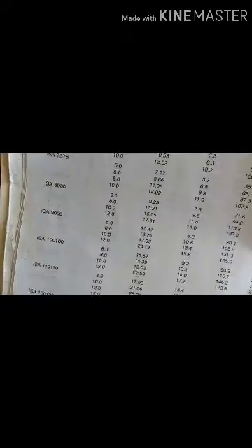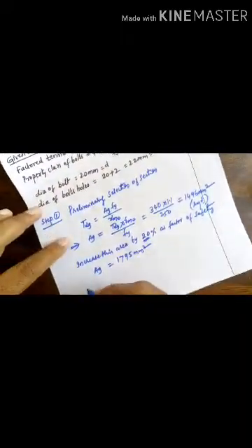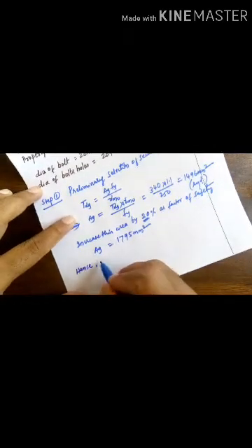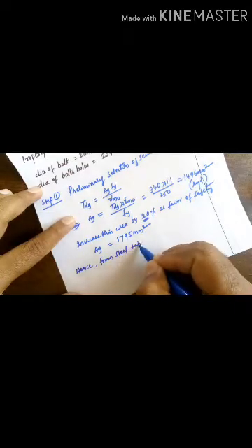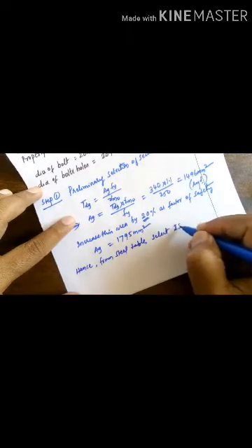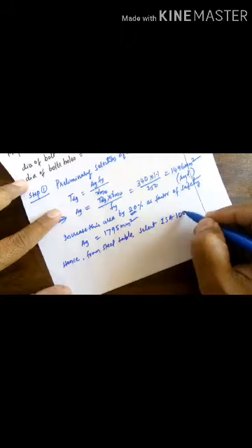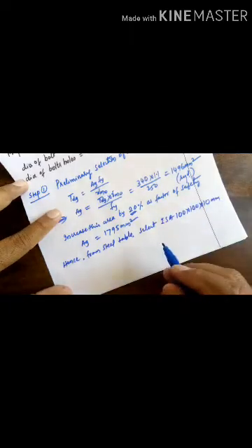So it is almost nearer to that area, that is 100 by 100 by 10, 19.03, that is 1903 millimeter square. Hence from the steel table select ISA 100 by 100 by 10 mm.